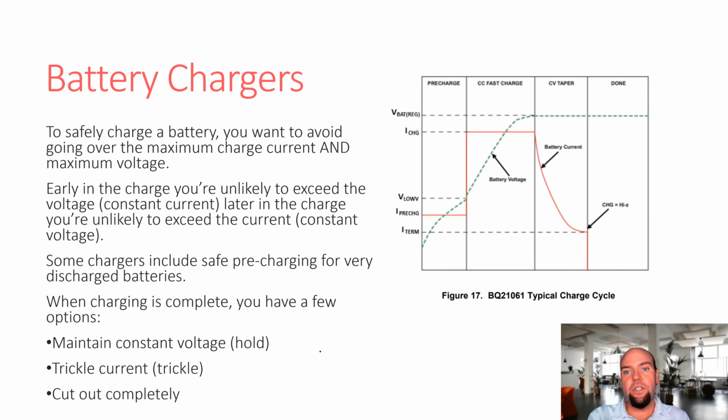But having a voltage limit and a current limit means that charging has to go through a process. The process starts when a battery is discharged. It starts with a constant current mode, where the battery current is constant until the voltage of the battery reaches some threshold, at which point it switches to a constant voltage mode, where the voltage stays the same and the charge current drops.